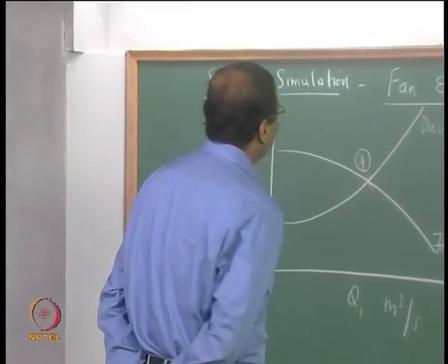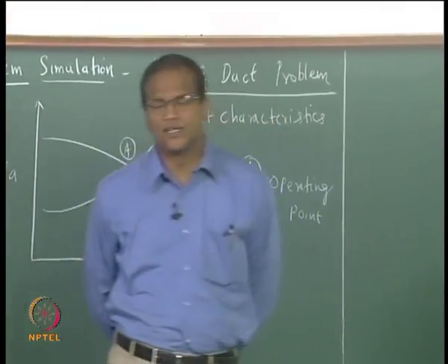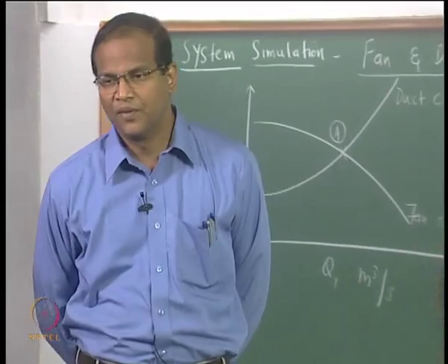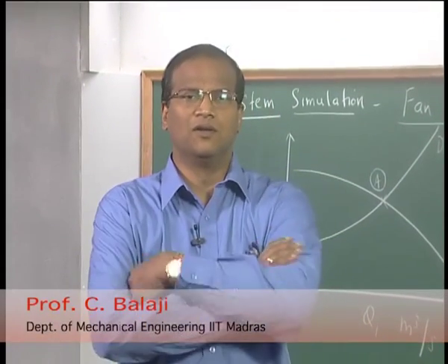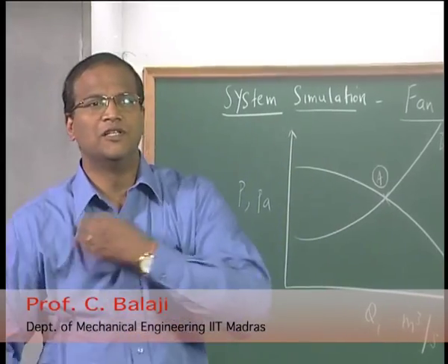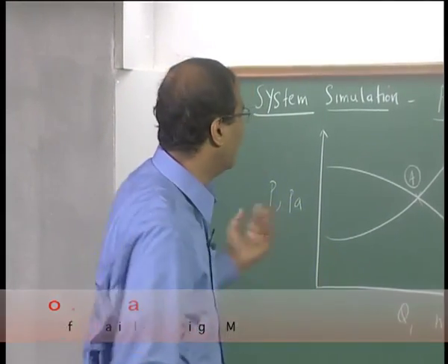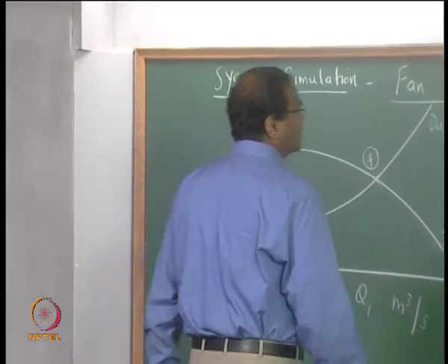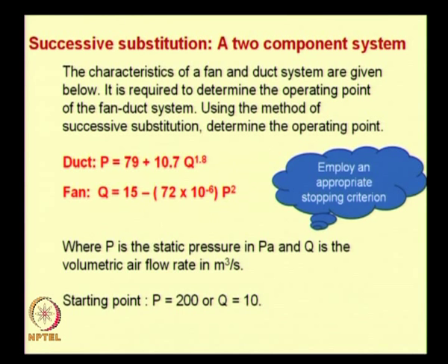Good morning. So we will continue our discussion on successive substitution. As you may recall, we are now working on successive substitution for a two component system. The specific system we have in mind is the fan duct system. So the equations for the duct and fan are given. I have already dictated this problem to you.